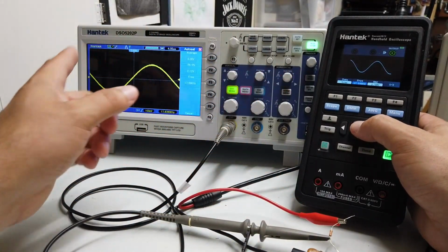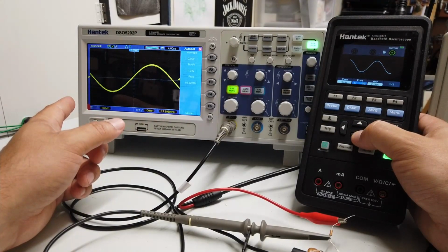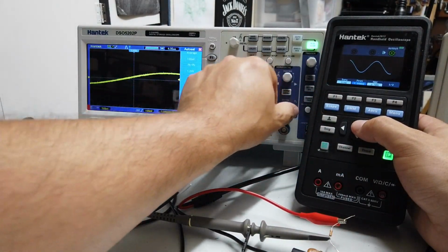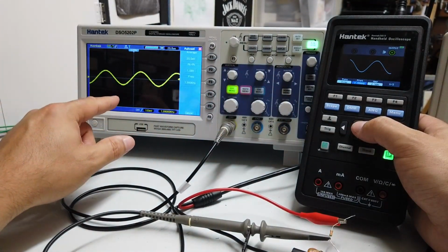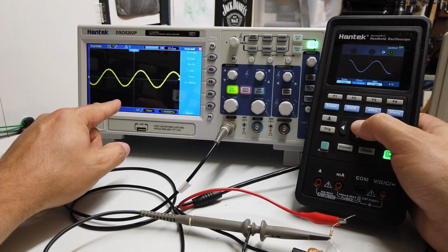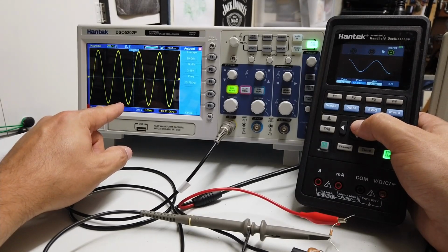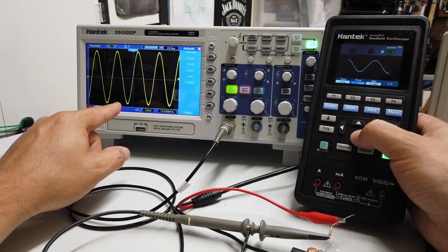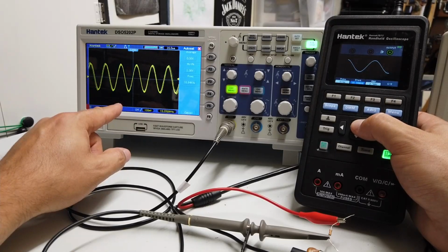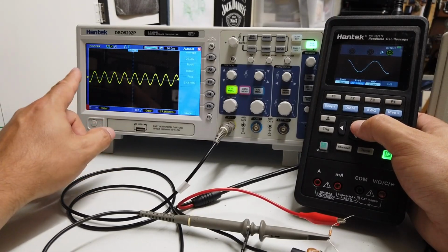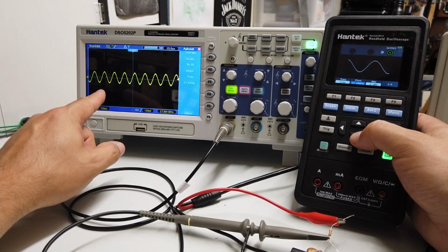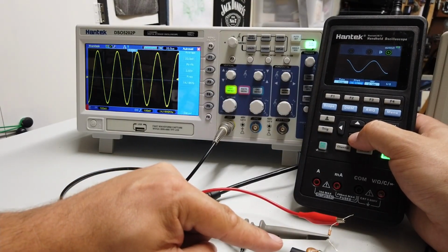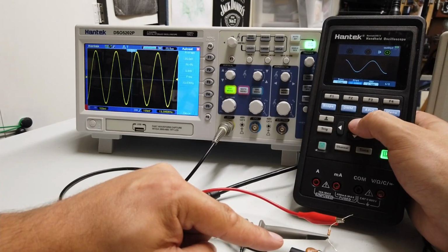And you see if we can go too far in one direction. So let's just keep going. There we go. So 7 kilohertz, and let's just change the time base so you can see that a little easier. So this is now 7 kilohertz, and we get this peak that comes in at about 13 kilohertz, 14 kilohertz. Yeah, and then if we go past that 14 kilohertz, you can see that amplitude diminishing there. And ultimately, what that's doing is telling us that this tuned tank is tuned to around 14 kilohertz.